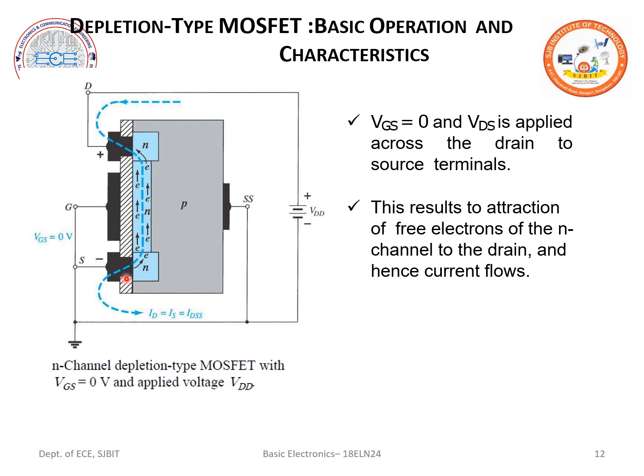So when we look into this, we have the p-type substrate and the n channel. The n channel runs throughout the p substrate, and on that we have the silicon dioxide layer, and proper holes are made to dope the n-type material to form a source and drain, right? So this is the construction principle we studied. Now let us look into the working principle.